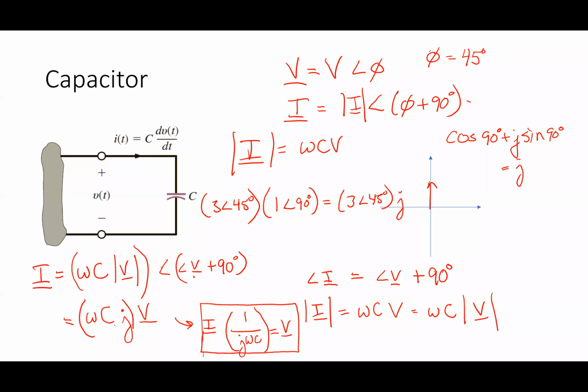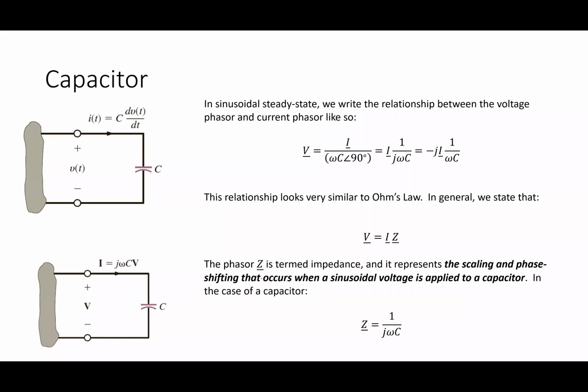if I look at this statement, the fact that I, the phasor, equals j times omega C times V, all I did was some algebra. So it looks like I have I times something equals the voltage. Everything in this is known before I start a problem. What does that look like? Ohm's law. I times something that's known about the circuit is equal to the voltage. I call that the impedance. That is the general term that we use when we talk about circuits.